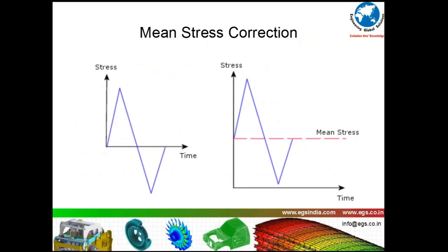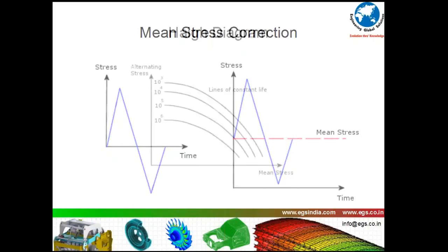So if you were to increase the life cycle of your components without attracting additional costs, your assembly stresses coming as a result of the compressive stresses would help you to get more mileage for no cost at all. These are considerations that you can make at the design stage. Employ it by looking at different pros and cons, and your tightening torque will influence your fatigue life.